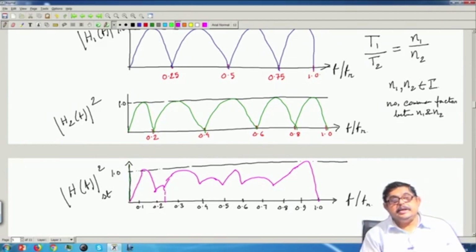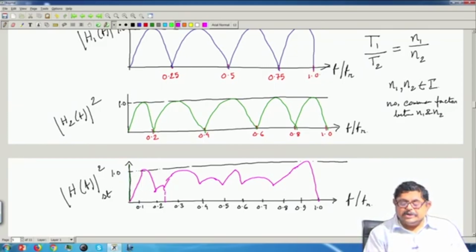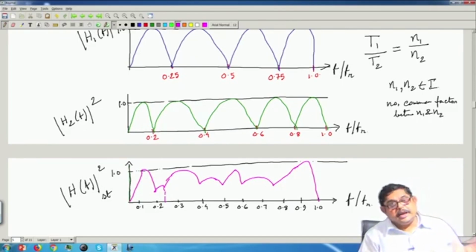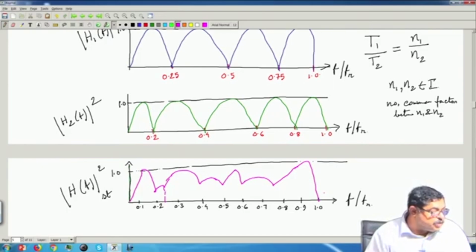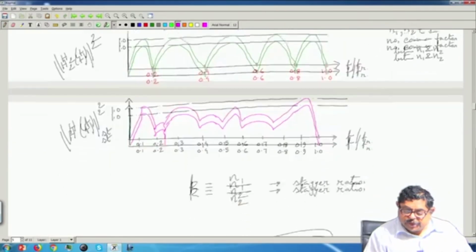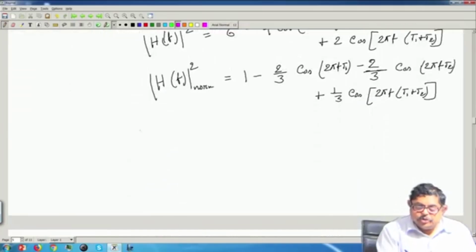But we know the technique that if we put the proper recursive filter, then this thing can be easily handled, because if we could make that sine square type of thing uniform. Making it uniform is not a problem with the recursive filter. Now, the question is how far we have advanced, that means how far we are successful in pushing the blind speed. So, we will now calculate that first blind speed will occur